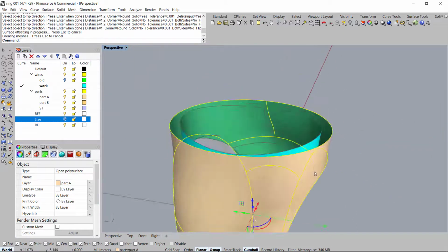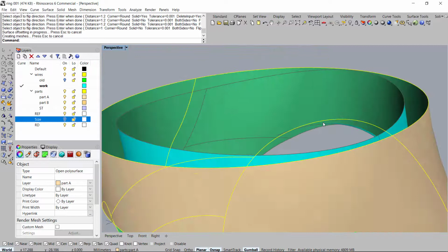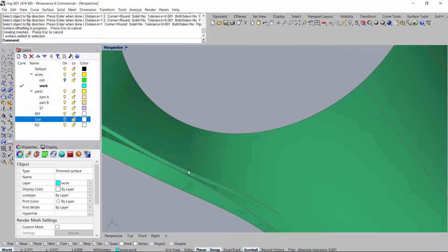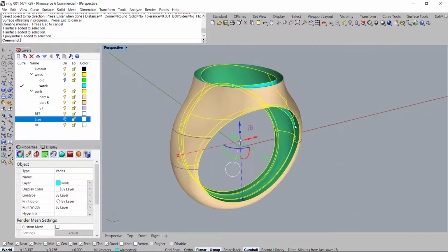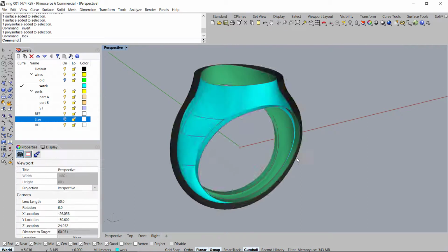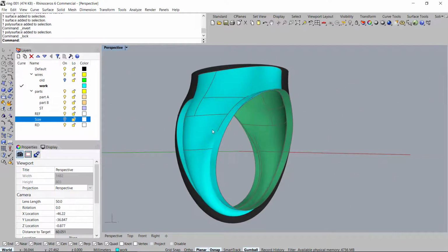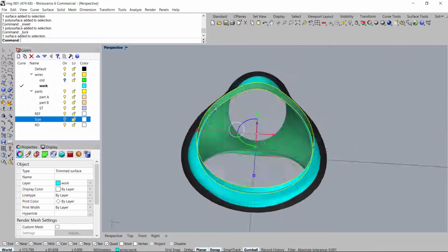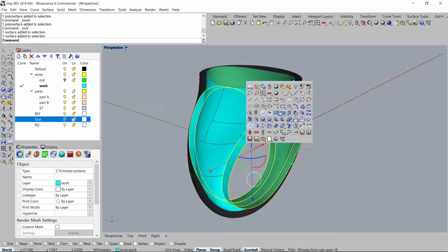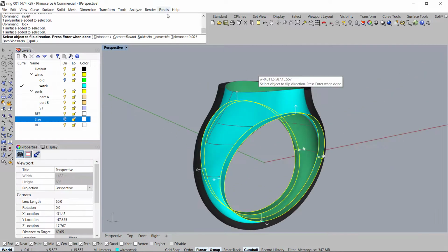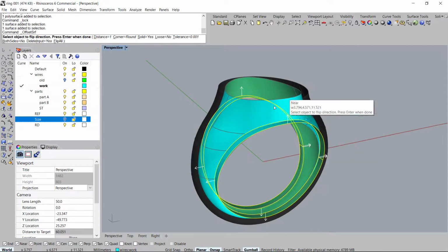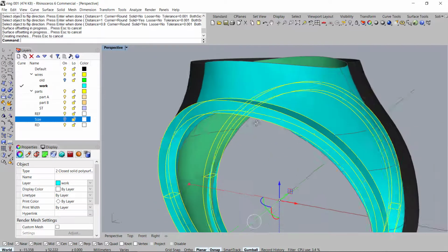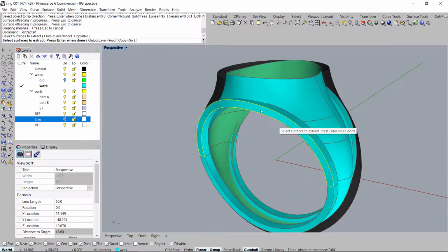The only thing left to do now is to blend the border curve to the actual inner offset. Okay, so I'm going to select just the border surfaces and the inner, and lock everything else. You can see this is what we need to blend together. Okay, we'll select these 2 surfaces. I'm going to offset. This time I will make sure solid yes is on, and the offset, we can go with a low number like 0.8. Okay, now that we have that, let's go ahead and just extract the outer surfaces.